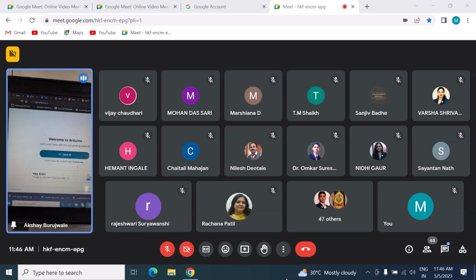So if you have a device connected with IoT without a network or a long distance network, we can use a LoRa kind of device for the wireless communication. If we go for wireless communication, the smallest device we call Bluetooth, and second we call Wi-Fi. Third is BLE, now an advanced device. Then we have Zigbee, which provides more range as compared to ESP8266 and rather small wireless devices, and like the ASK module, which provides 20, 30 meters of wireless connectivity. Zigbee is more industrial and provides up to 100 meters, 300 meters, 500 meters of connectivity. It depends on the constructional field. In an open field, it shows a longer distance, but in a construction field, it reduces the length of the communication.